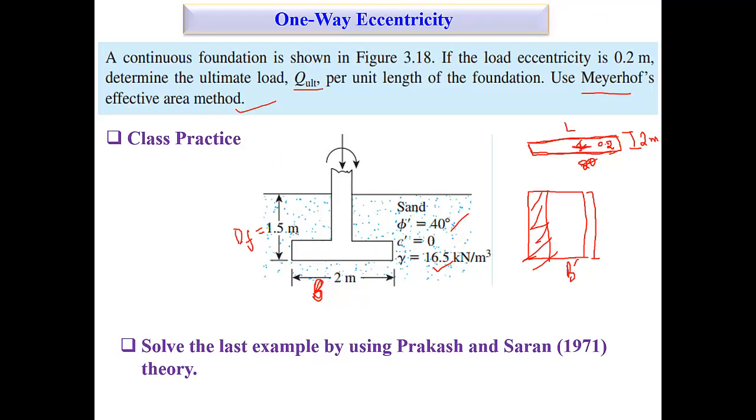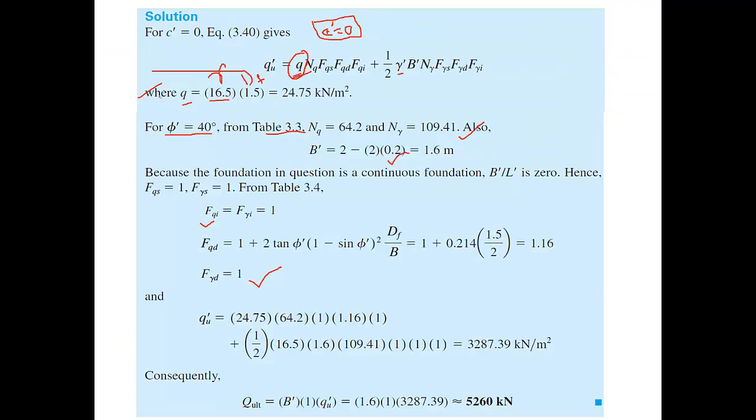If you multiply 1.5 and 16.5, this is the unit weight per volume. If you multiply it by one distance, it gives you per area. So weight per area, or load per area, is what? Stress. So q is stress, in newton per meter squared. Yes, sir.